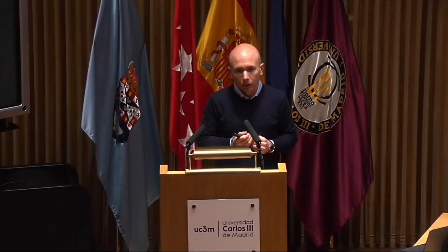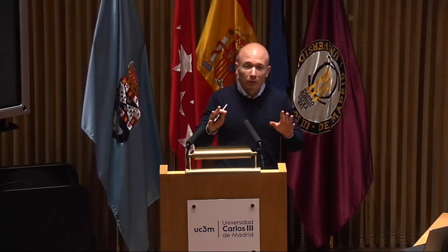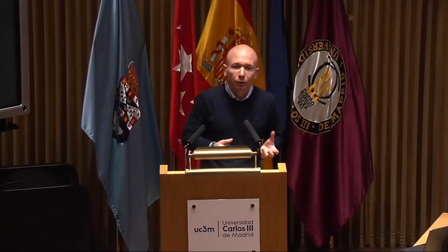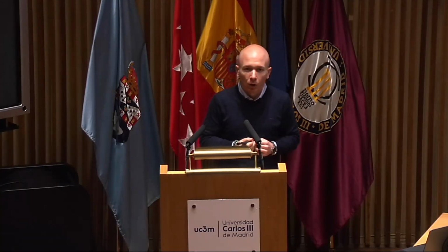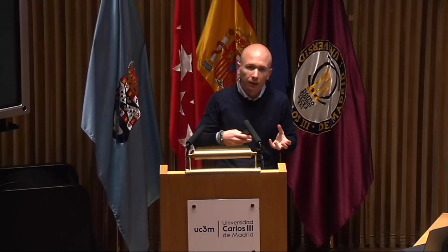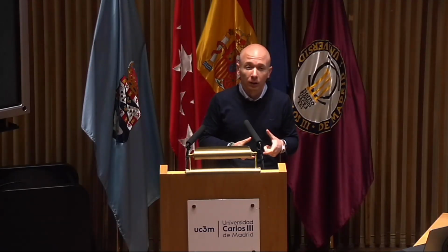Okay, and then my guess is that the difference that you observe between the boundary layers in the 2 facilities has to do with the tripping of the boundary layers? No, in the facility it is simply a turbulent boundary layer that evolves because the Reynolds number is high. It's due to the fact that the 2 facilities are different in terms of the structure of the facility, the way in which the first convergent is designed, and the duct sizes are very different.